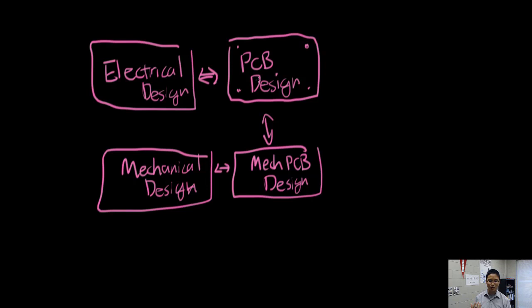So have the fasteners or whatever approach you want to take selected, have your standoffs selected, and make sure that the required dimensions are incorporated in your printed circuit board layout. And another important thing to keep in mind is that when you mount the PCB, there might be a certain amount of flex as you tighten it. So also make sure that you have a certain amount of clearance of your components away from the clearance holes, especially in the case where, say, you have ceramic parts or parts that are very brittle. You definitely don't want them close to these through holes where flexing might occur and your parts might break.